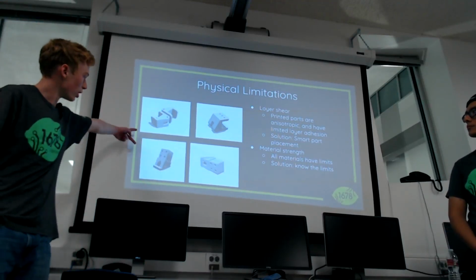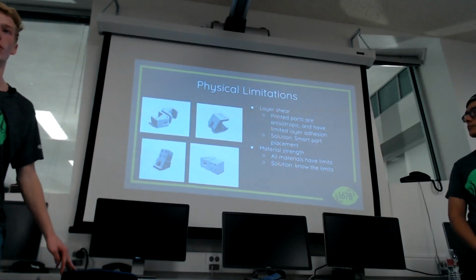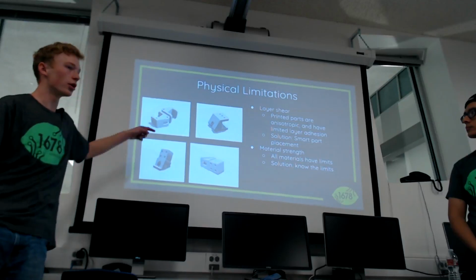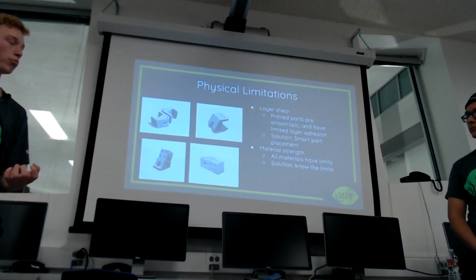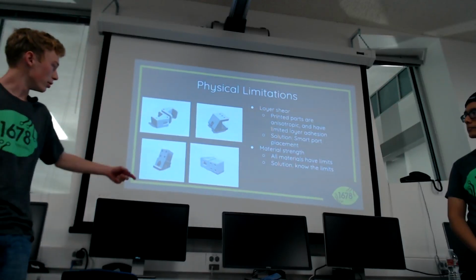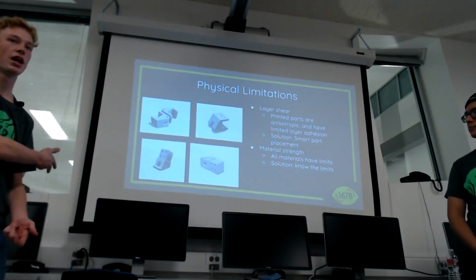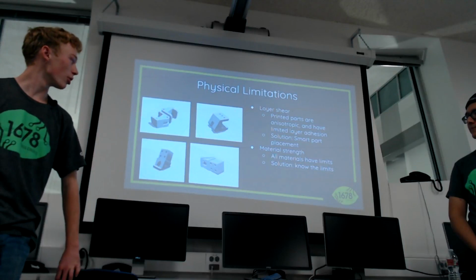Both these pictures on the left were my first attempt at printing a part. Both of these failed. In this case, these horizontal holes right here blew out because there were some bolts in them. And this one right here, it was supporting a tube coming off at an angle like this, and the whole thing ripped in half when our elevator was flopping around for a little bit.